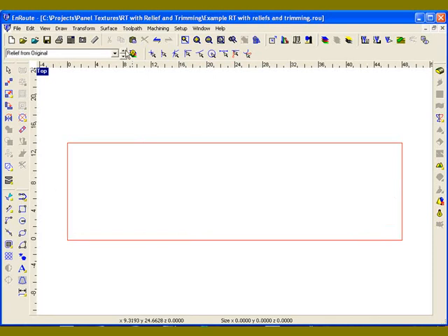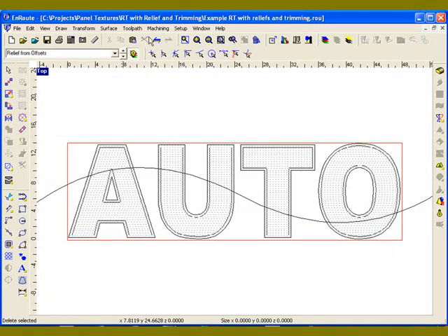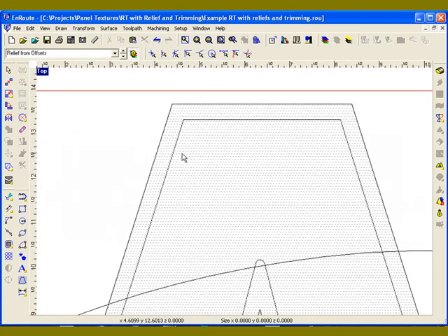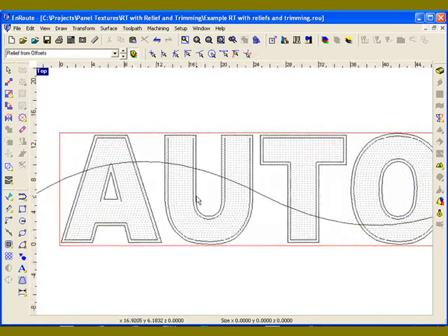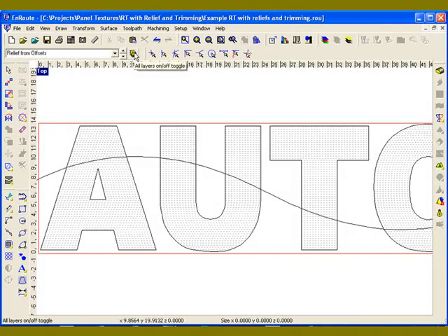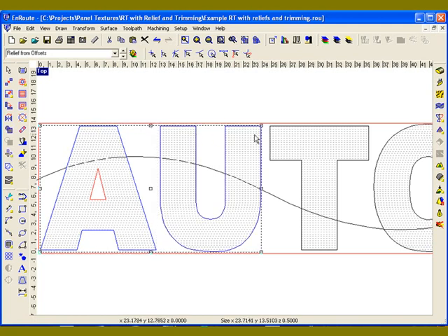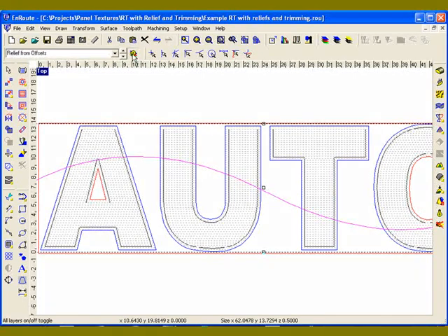So what I did is I just created an offset from my original artwork and then applied the relief to that. So I offset by 3/10 of an inch in this case, and created that offset from the original artwork. So going into it, first thing I want to select my reliefs and select my seed contour. Now I'm going to turn my original artwork on because I'm going to use that as the definition of the perimeter for the rapid texture contours.